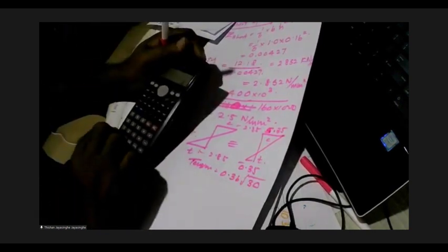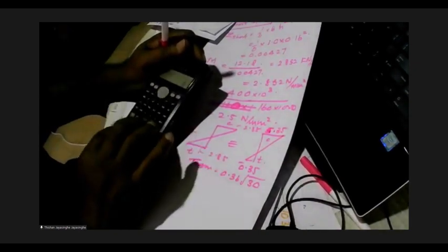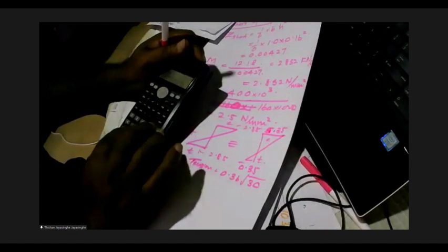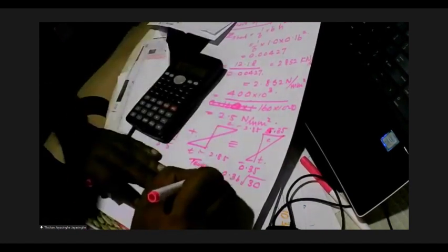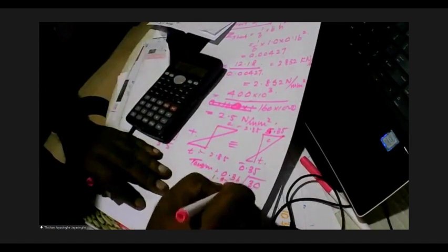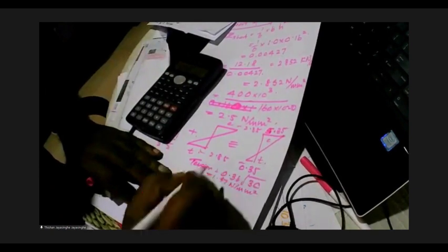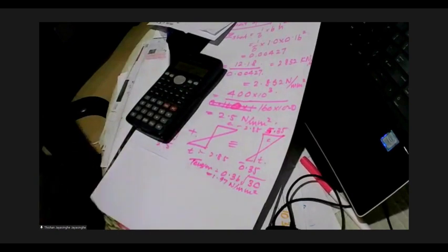So now you can see why we can use about 30 megapascal concrete. Square root of 30 multiplied by 0.36, you get about 1.97. Allowable stress 1.97.